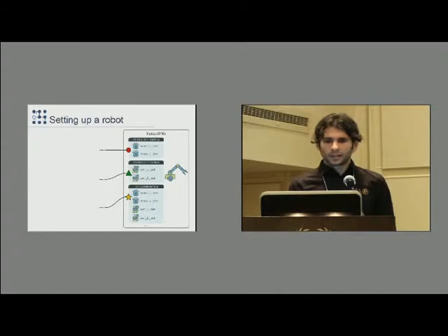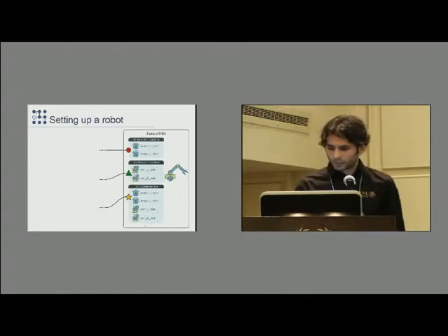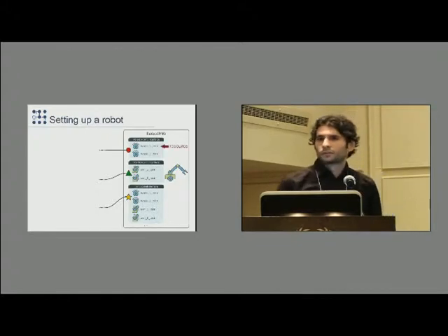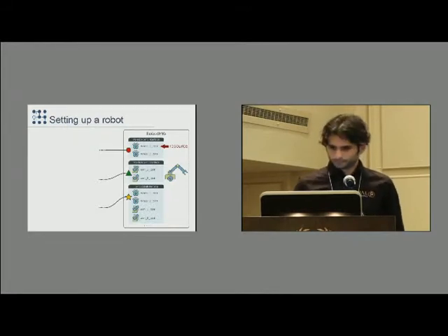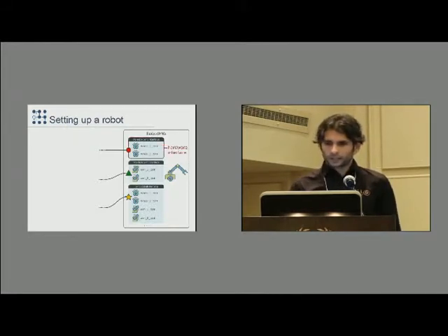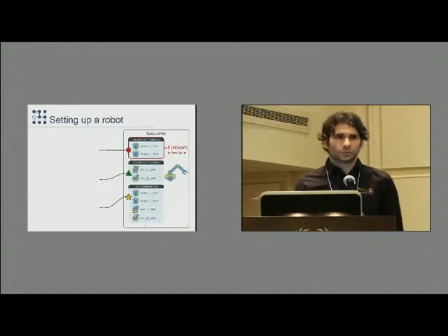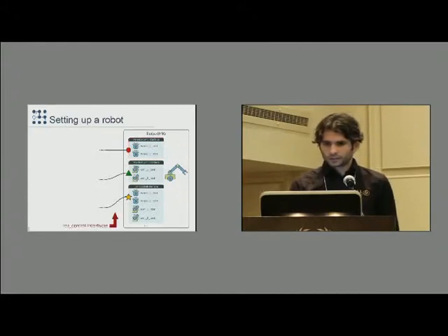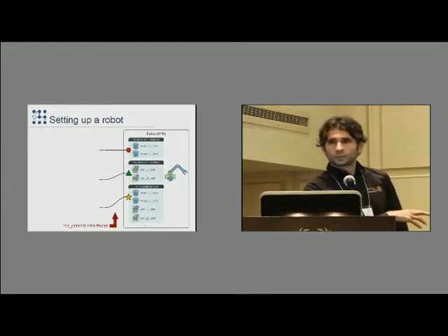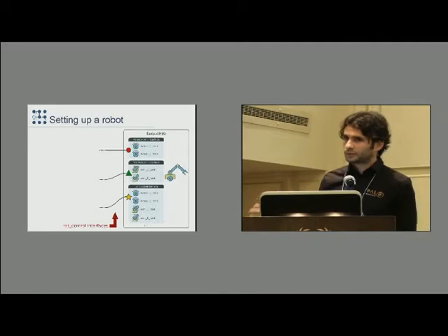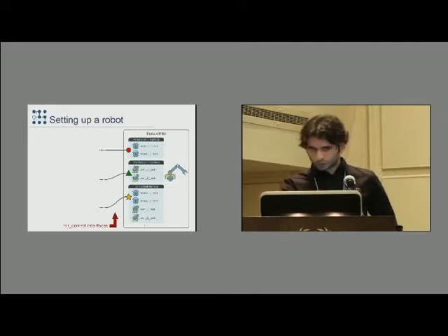We zoom in. So in ROS Control speak, we have the notion of resources, as for example, a velocity-controlled wheel. Then we have hardware interfaces, which is just a set of similar resources. And then if you pile up a bunch of interfaces, then you get a robot. Then there's these connectors here, which are ROS Control interfaces, not to be confused with typical ROS interfaces like topics or actions or services. This is not that. In the end, we're just passing pointers around. This is something that is real-time safe.